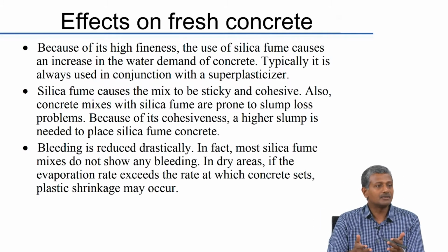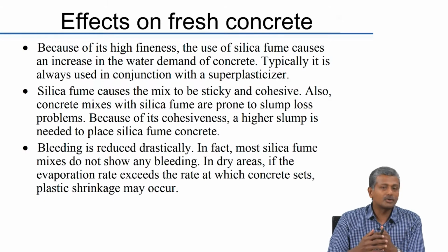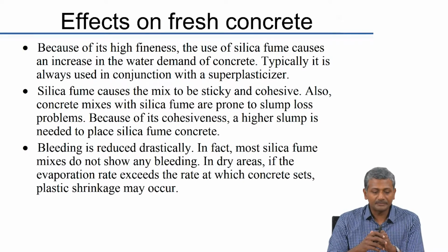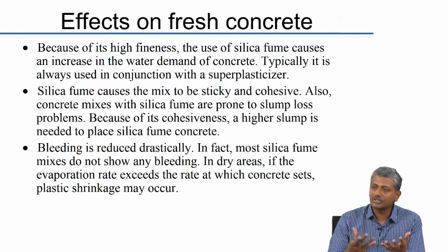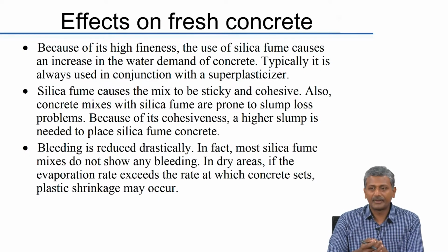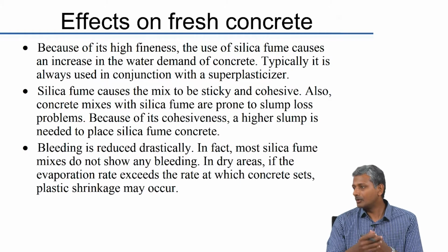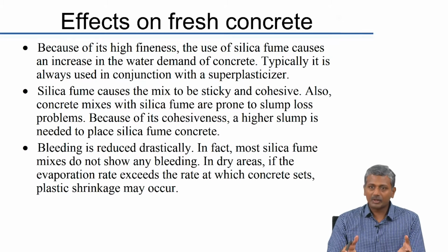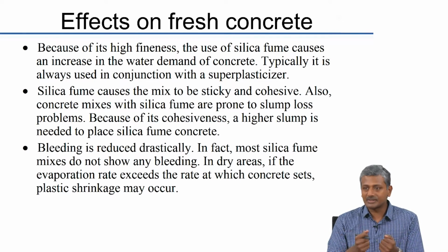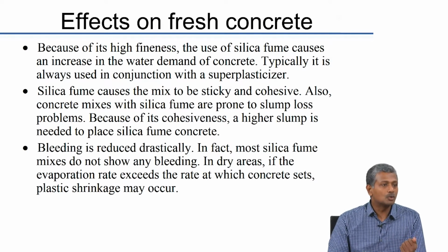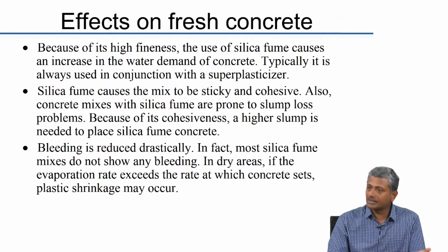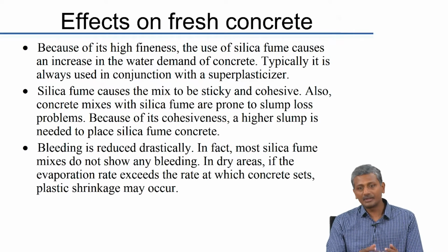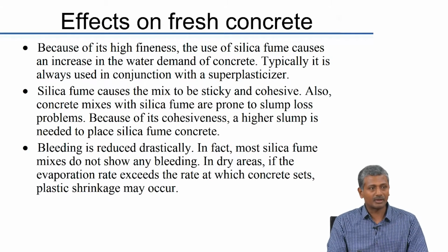Now, with silica fume, since there is going to be no bleeding, your concrete is going to be susceptible to drying from early stage itself. Now, what do you think is the problem with that? Plastic shrinkage, essentially shrinkage of the concrete while it is still fresh, and that will lead to cracking, right, because only the surface of the concrete wants to shrink, the rest of the concrete is dimensionally stable, because of which there is a restraint which causes the cracks to appear on the surface. Again, not a structural issue, we will discuss more about this later, but you do not want obviously surface cracks to appear, because aesthetically it is a problem. Secondly, durability may be an issue, because if there is cracking, obviously water can get into the cracks.